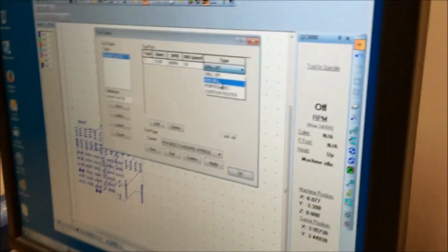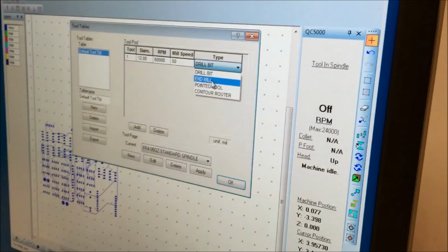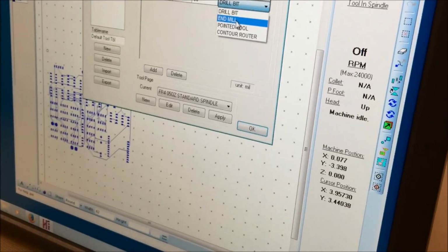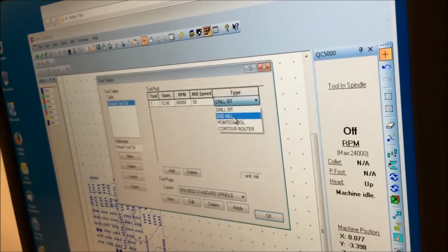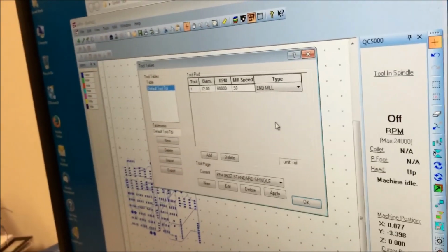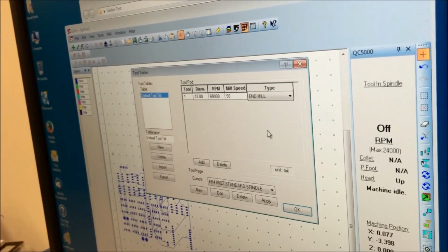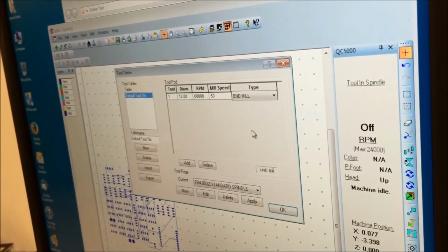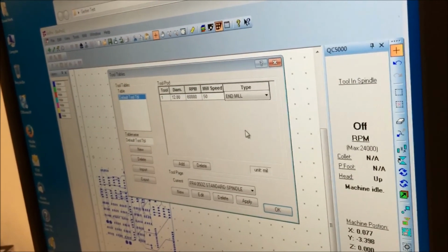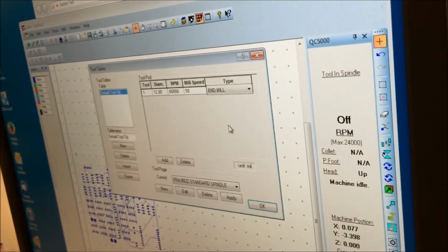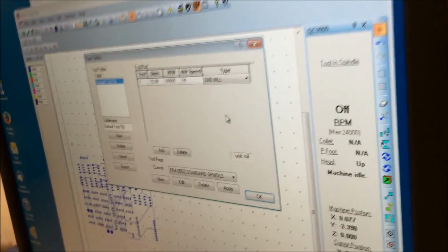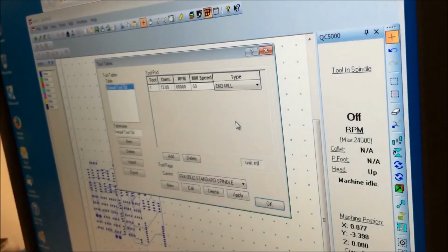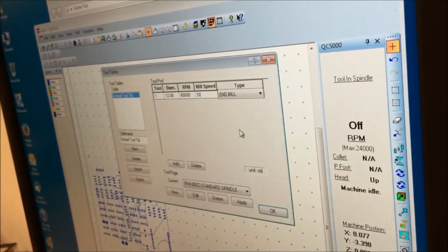And so for this mill that you've chosen, did you say 10 mils? The 12. This is 12 mils. This is the T1 mill. So does your design allow for 12 mil spacing between traces? That's something that is done in the Eagle file. Right, but how do you know? If you needed smaller than 12 mil spaces, will this software tell you that you also now need to load a narrower bit?